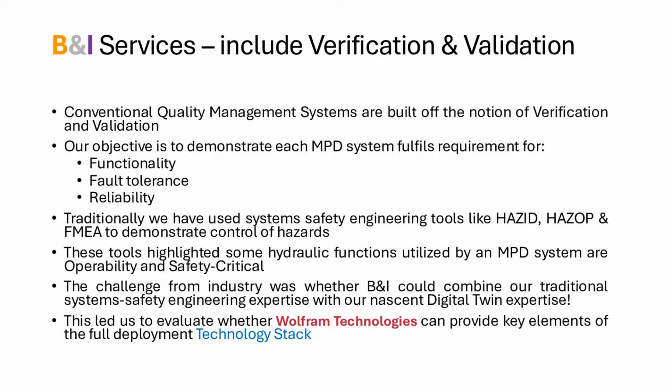Traditionally, we've used system safety engineering tools like hazards and operability, and failure modes and effects analysis to demonstrate control of hazards. Now, these tools have highlighted some hydraulic functions utilized by an MPD system are operability and safety critical. So the challenge to us at BNI from the industry was whether we could combine our traditional system safety engineering expertise with our nascent digital twin expertise. This led us to evaluate whether Wolfram technologies can provide key elements of the technology stack for delivering a product.